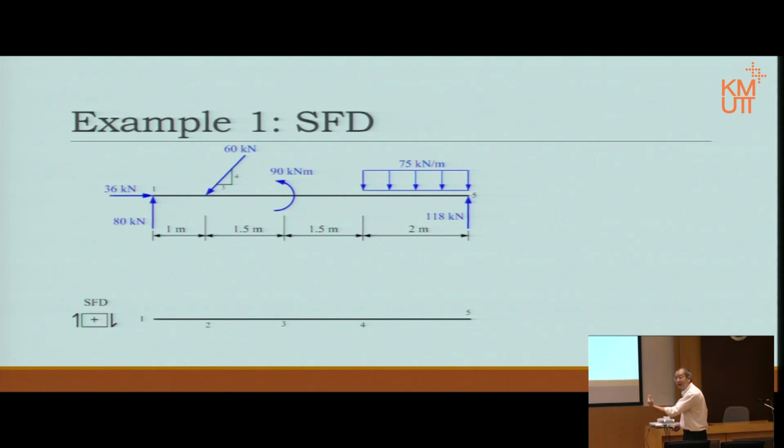Well, or at least not shear force that we're concerned with. So the shear force of the beam outside the beam is 0. It doesn't exist. Now you move on to point 1, then you are hit by 36 kilonewton. 36 kilonewton is not 90 degree. When we prove the shear force, we use 90 degree forces, or in fact the force on the same line as the shear. So 90 degree to the beam in this case.